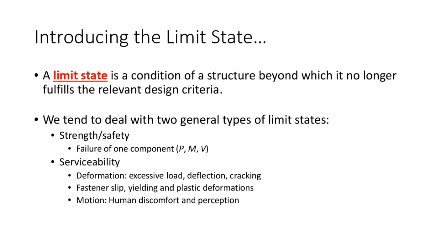So when I start applying load factors, you'll see how in some of our load combinations, the load factors associated with the live loads are higher. We do that because we have more uncertainty associated with the live loads. That concept will be a little bit more clear on Friday, and it goes into the different design philosophies that we can use. One of them you're very familiar with, which is just to use a blanket factor of safety. Like, here's the capacity, let's just divide it by 2. And the other is a more refined one called LRFD, which is what we'll use throughout the semester.